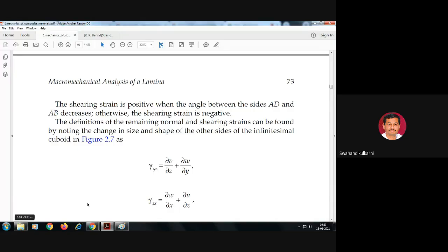In this case, as far as composite material is concerned, it need not be isotropic, because the reinforcement remains an inherent phase and does not mix with the matrix material. In alloys, when two materials are combined, say a parent material and an additional material, they give a homogeneous structure.